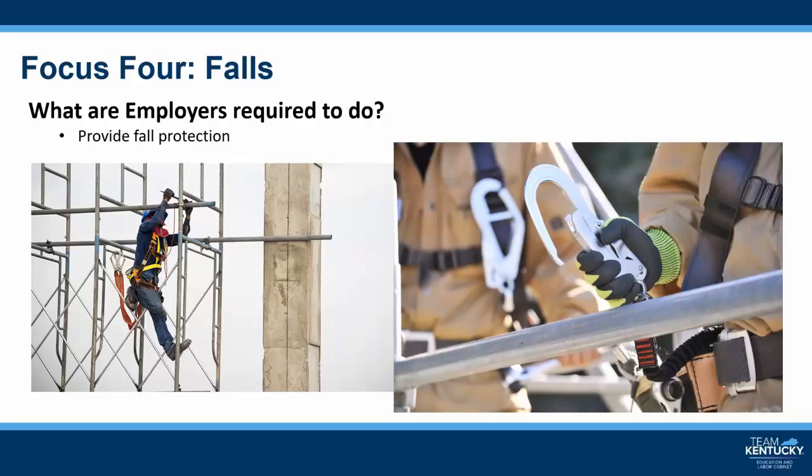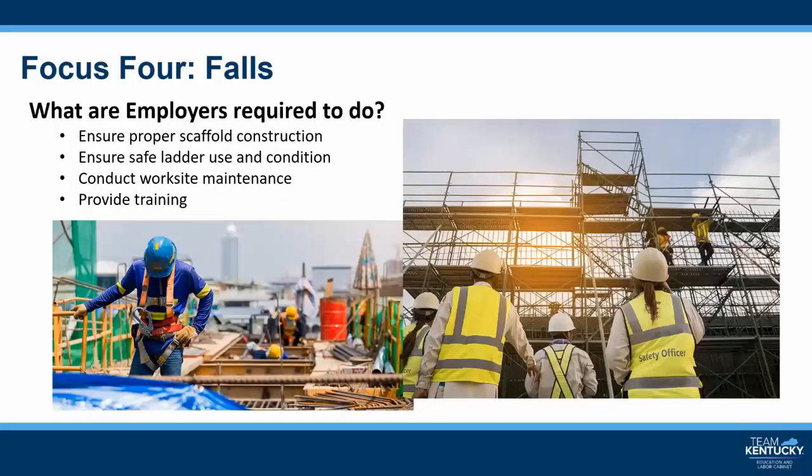Employers should also emphasize fall hazards that are unique to the site, such as open floor holes or shafts, riser penetrations, and skylights. What else are employers required to do in relation to falls? Employers should ensure proper scaffold construction. Employers must construct all scaffolds according to the manufacturer's instructions.